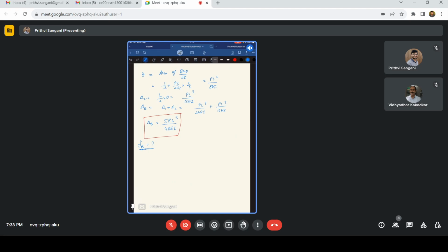So again we have 3, 3, and 3. So we have 9 internal forces which are going to generate there, right? But you need to understand that whatever forces are generated here can be solved using these forces, right? If we are able to solve for these forces, we can directly solve these forces. And in this case, unknowns are 9. Okay, we have 9 unknowns.